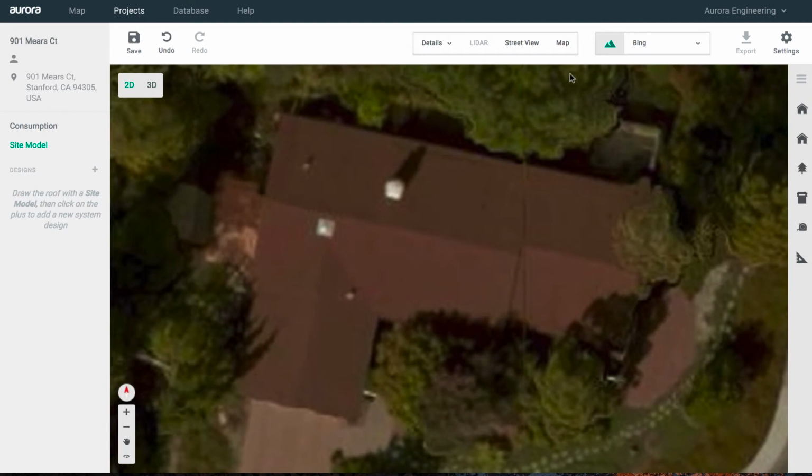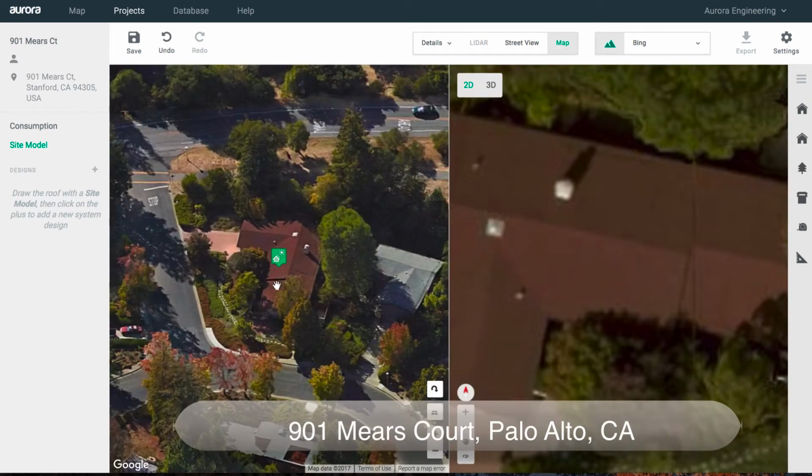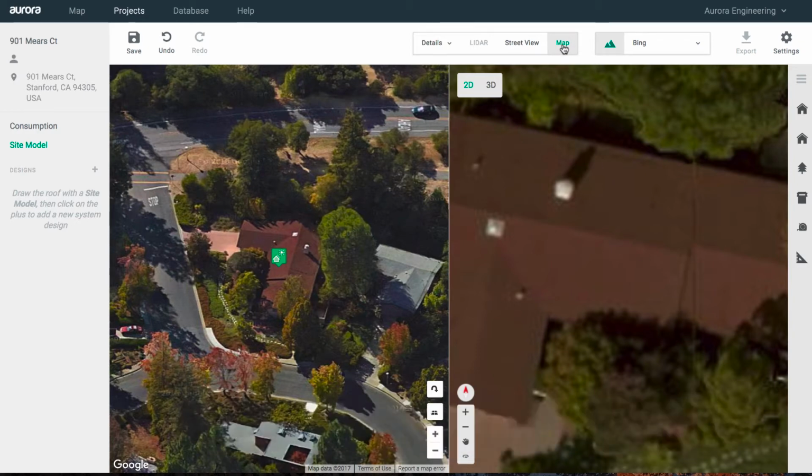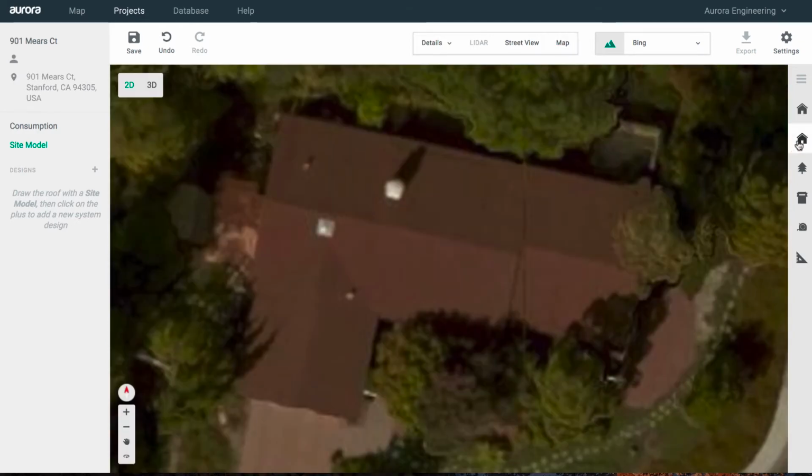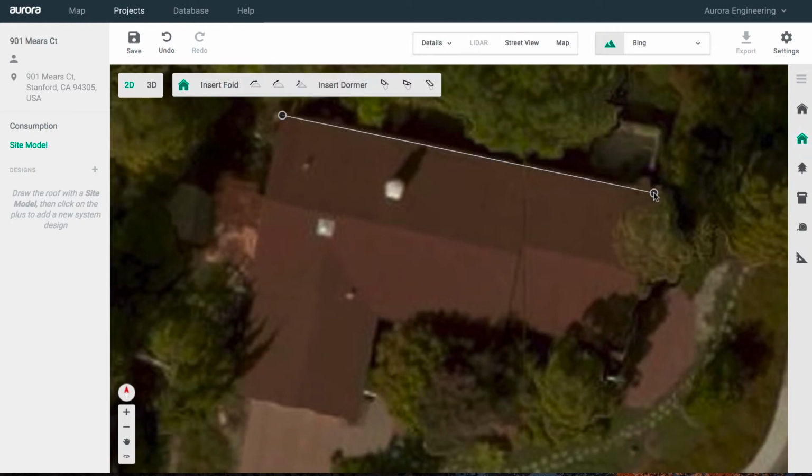In our next example, we'll go into how to model split edges, which you can see from the map view over here is that little split you see in the roof surface. Go ahead and get started as before. Just outline the vertices of this particular roof and click on the corners of the building. You'll notice there's a little jog over here, which is where the split occurs. I like to use the tracking lines to help guide my movement.